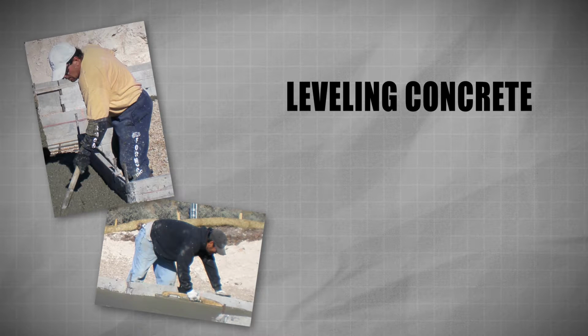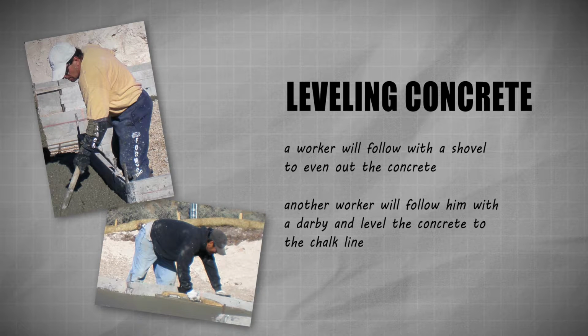Another worker will follow closely behind the pump with a shovel, and they will use the shovel to grade and level the concrete to the chalk line. Another worker will follow behind with a derby. They will evenly flatten and smooth out the concrete to the level of the chalk line.